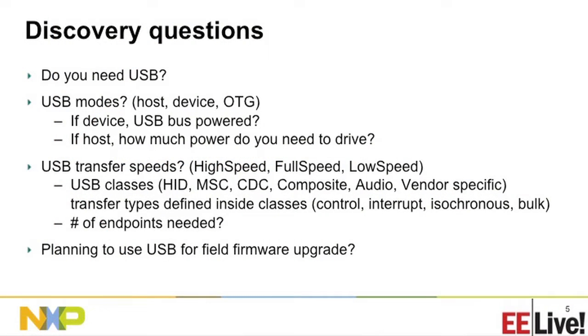Sure. So I think since you're here, you must be interested in USB. So do you need USB? What USB modes are you considering? Do you want to do host, device, or OTG? Some other considerations are whether you want to have your USB system as bus-powered or self-powered. How much power do you need to drive if you're a host?